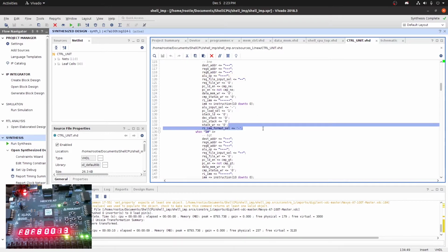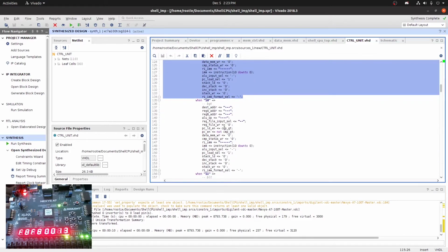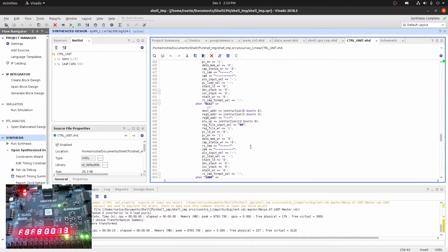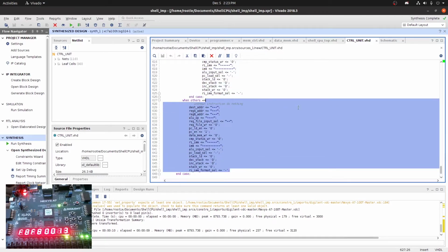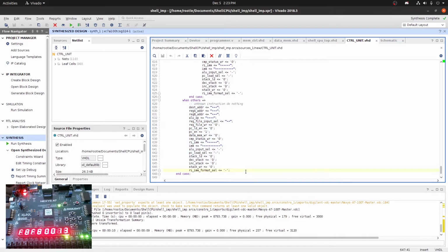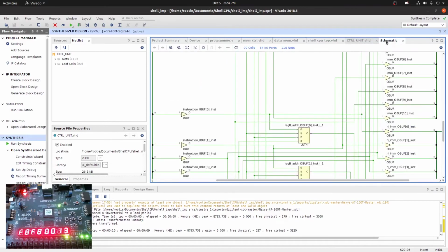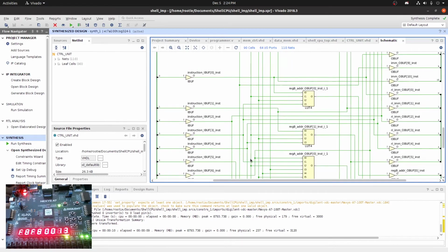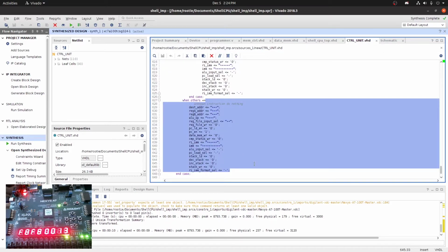I think it wasn't stressed enough in previous classes that when you design these, you have to cover every option. So your control unit ends up being this long file, and it would help a bunch of students with that. So maybe it's important to mention in previous classes that this can happen, and you should probably be looking at your post-synthesis schematic to figure out what exactly is going on, and not relying too much on looking at the code and figuring out why it's not working from your timing diagrams.